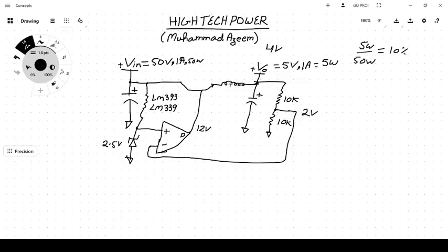The property of the inductor is that in the inductor the current lags behind. So suppose the transistor was on. The transistor is switching, sometimes turning on, sometimes turning off, so that the output voltage remains fixed at 5 volts. Suppose it was previously turning on, and now the 5 volts has exceeded to 6 volts, so now it's time to turn off the transistor. The comparator gives the command to turn off the transistor, so the input path is blocked, but we know that the current in the inductor lags.